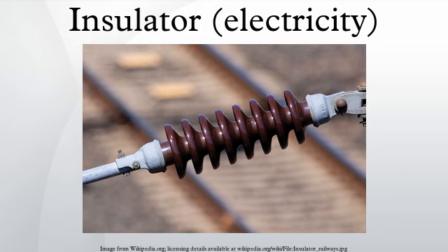Insulation materials that perform well at power and low frequencies may be unsatisfactory at radio frequency, due to heating from excessive dielectric dissipation. Electrical wires may be insulated with polyethylene, cross-linked polyethylene, PVC, Kapton, rubber-like polymers, oil-impregnated paper, Teflon, silicon, or modified ethylene tetrafluoroethylene. Larger power cables may use compressed inorganic powder, depending on the application.